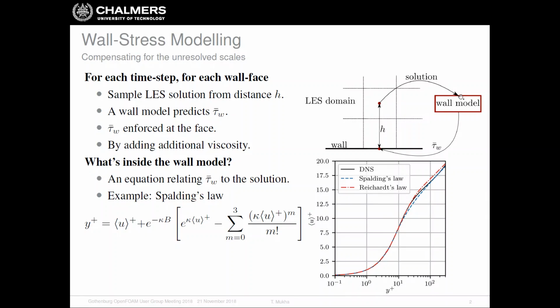And we're going to put that in this box called the wall model. More about what is inside the box later, but what we're going to say now is that the job of the wall model is to predict the filtered wall shear stress. So the wall model gets the solution as the input and gives you the wall shear stress at this point as output.